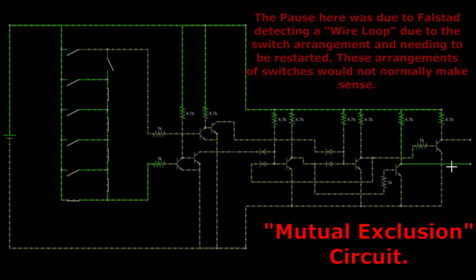So we put the lift in the middle position, and then we turn a call on at the very top level. So you can see here, top's come on, and again, up direction has been selected. So now let's select at the bottom as well. So now we've got top and bottom, but still only top. So if the elevator now moves up, continues to move up, when it finally services the top call, it will now change over to the bottom direction control, and the lift will continue in the opposite direction.